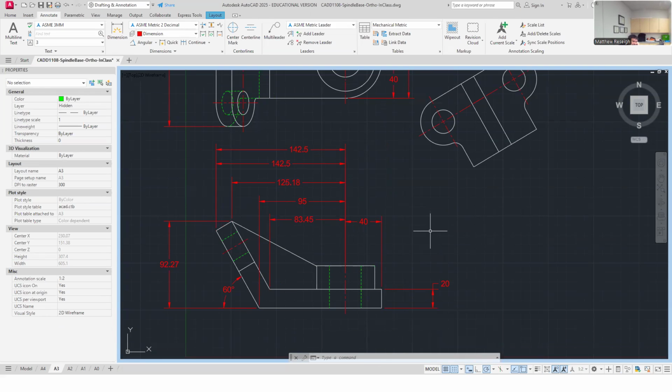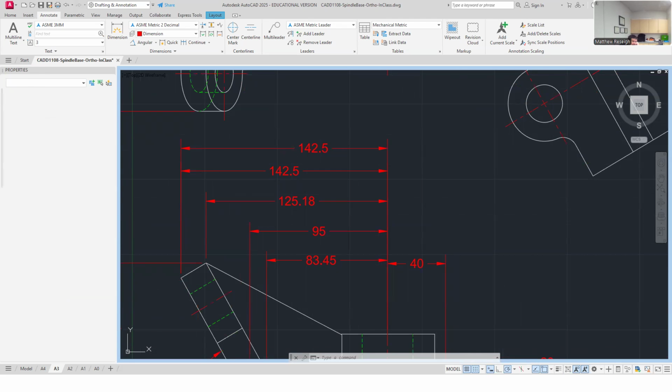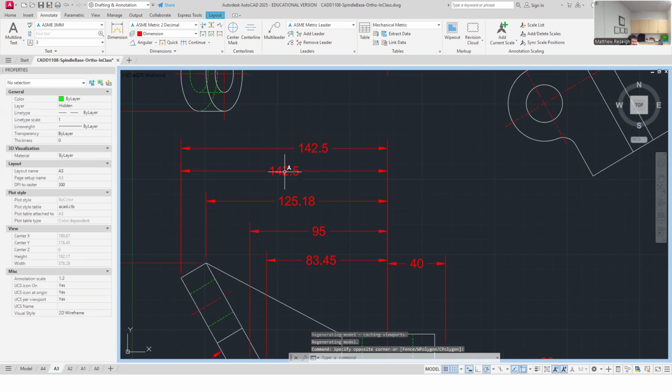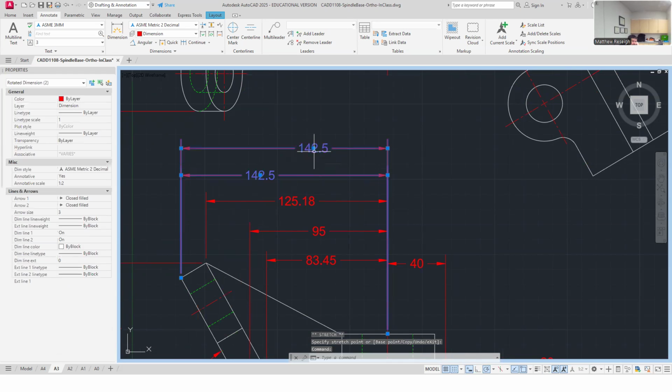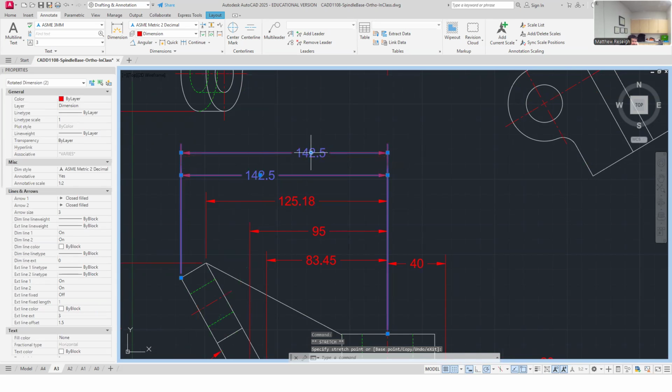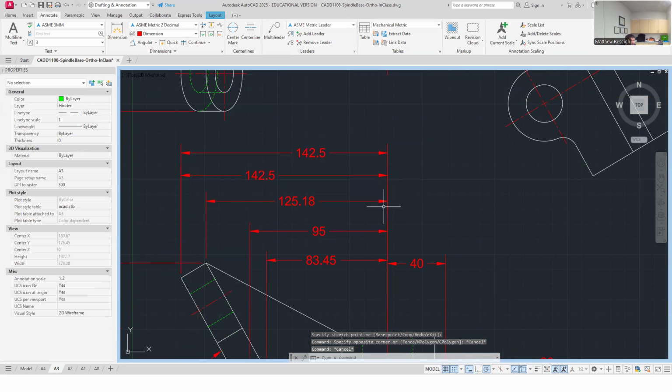Then I've got this double dimension, but they're different. They seem like double dimensions, but they're actually different features. So even though the dimension is the same, you go back and tell yourself, have I dimensioned the same feature? Then it's a true double dimension. These just happen to be the same dimension, but different feature points from the same datum.